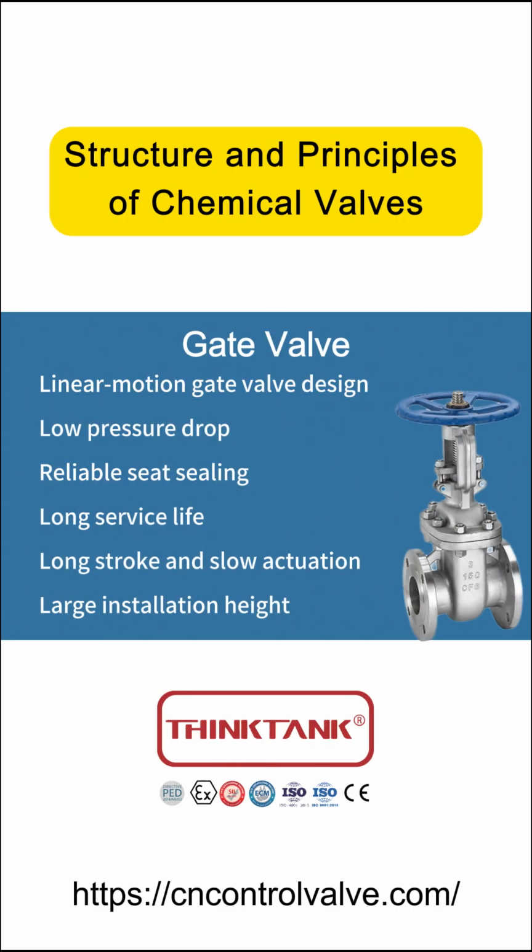Second, the gate valve. As one of the most common valves in the chemical industry, it is also one of the oldest, with a wide range of applications. The closing element of a gate valve is the gate itself. The gate moves perpendicular to the direction of the media flow. It achieves the shut-off of media in the pipeline by closing against the valve seat.